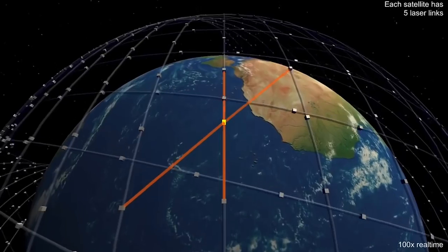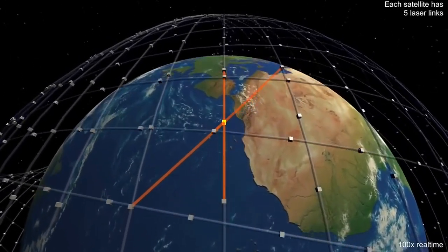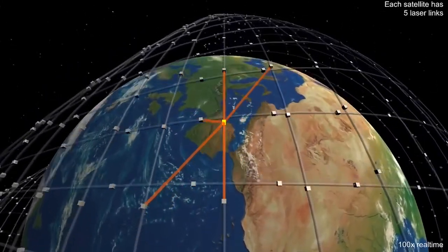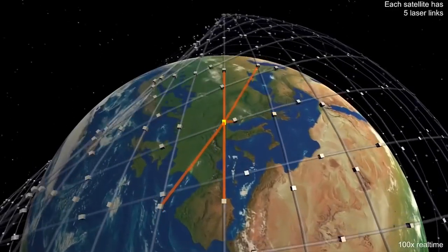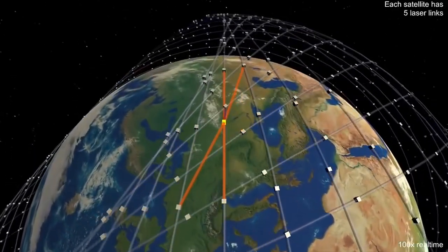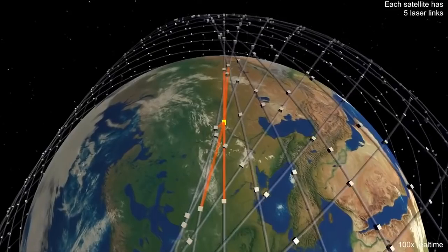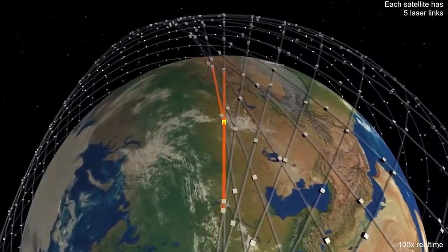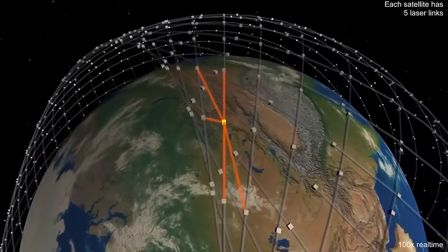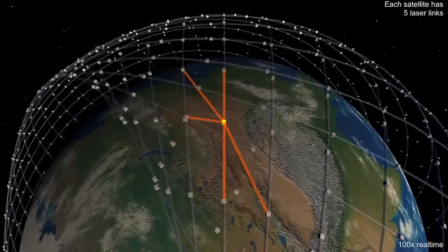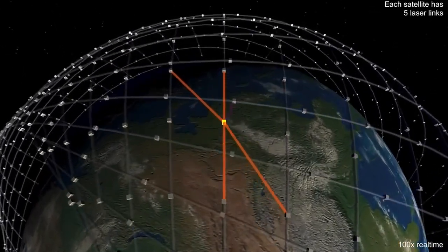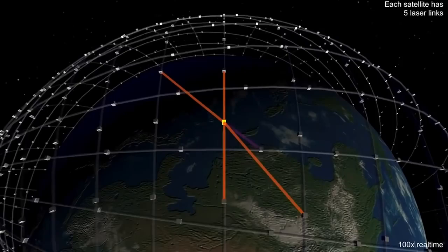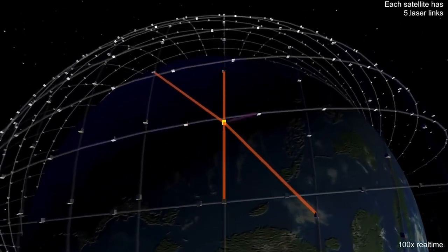As much of the population stretches around northern temperate latitudes, more long-distance communication goes east-west, so it makes sense to connect to neighboring satellites to the east and west, rather than to the nearest neighbors. This leaves northeast-bound satellites talking to their neighbors and southeast-bound satellites talking to theirs. We'll use the final laser link to communicate with satellites in crossing orbital planes.